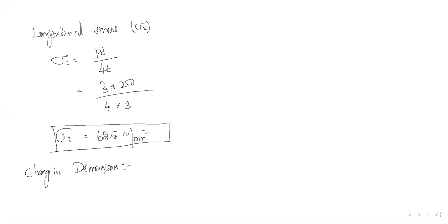Here, first we all know the circumferential strain, that is E1 is equal to sigma 1 divided by E minus mu into sigma 2 divided by E. The circumferential strain E1 is nothing but the change in diameter divided by original diameter, so from this we can directly calculate del D, the change in diameter.